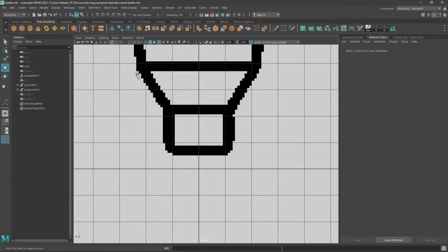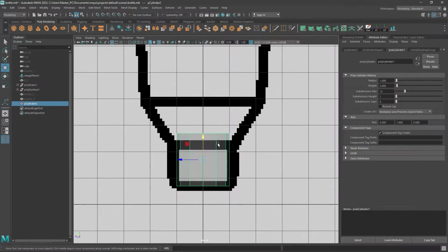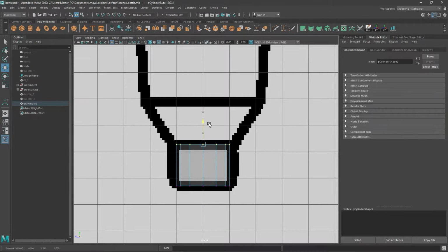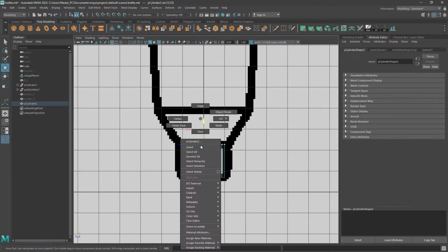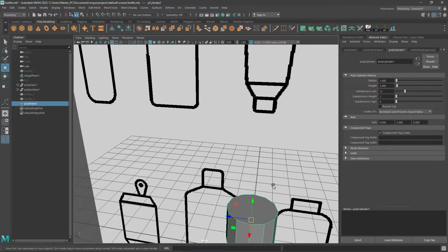Okay, so yeah, first you need to decrease this, then only you can scale it, otherwise it is gonna give some error. Okay, so I'm gonna put it like this. Yeah. Okay, cap is done. Now I'm gonna select this face and scale it up.